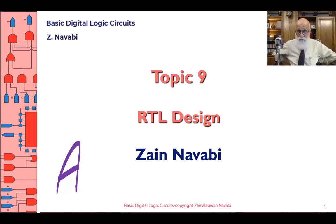And then the last thing we did was a serial adder, saying that bits are received on A and B, and we developed a circuit that will take these bits and then bit by bit add them into an 8-bit result, and then issue the result, and also issue a signal indicating that all the work is done. That was an RT level design. It was a very simple one, but it was an RT level design.